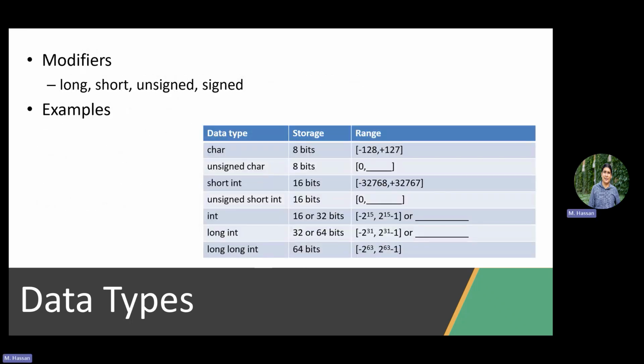More than this, it's not only about data types, but also modifiers of the data types. So it's not only about defining a character, for example, because a character is 8 bits. But what if you are indexing a register? Generally, an 8-bit character allows both signed and unsigned values, right? So with 8 bits, you go simply from negative 128 to positive 127. But if you're indexing a register, you will never expect an index to be negative, right? So it's more efficient to have all your 8 bits dedicated to positive numbers to enable a higher range. How do we do this?